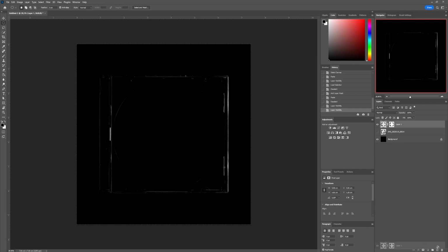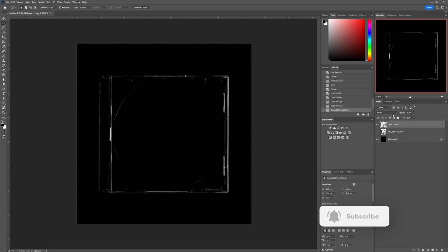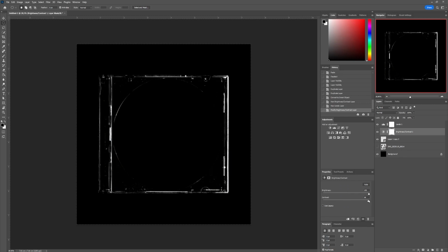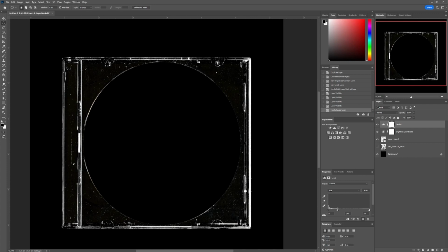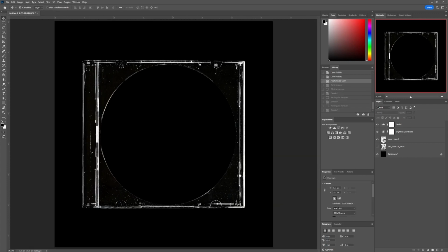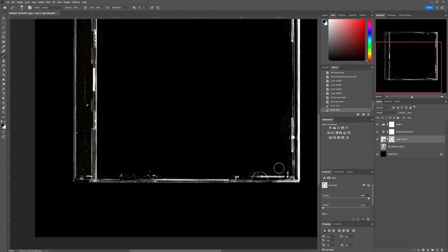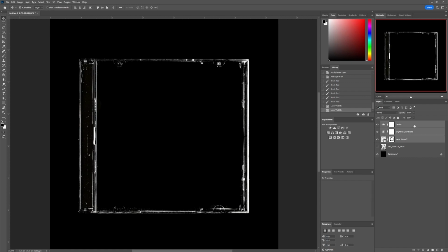As the mask also plays with transparency, we'll duplicate our layer several times to bring out more detail. Then we'll select our layers and convert them into a dynamic object. We'll add and adjust a brightness, contrast, and levels layer to accentuate the object's details. I'll crop the center of the box to remove the round area of the previous mask. Then convert everything into a dynamic object.